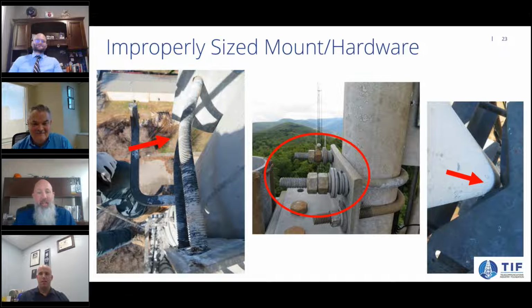No, this is, as funny as it is, if it doesn't fit, get a bigger hammer is not the best motto to use. As we look at the photo on the left, we've done numerous things. Well, one, we put a collar mount up that wasn't spec'd for the size of the pole. And in doing that, obviously, we bent some threaded rod.